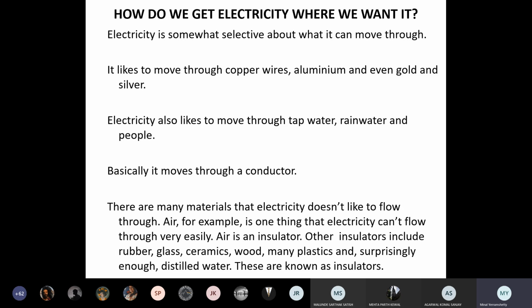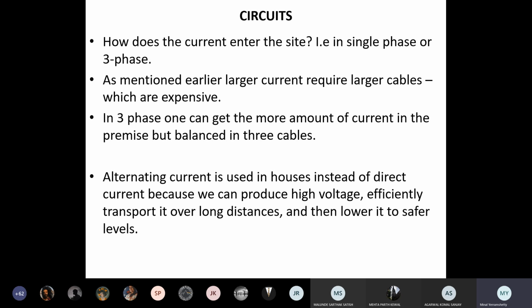And that's the reason why we have a plastic or rubber insulation around the live wire. Then you will see something in our college, this black colour thing. That is actually a thickened PVC covering, which works like a conduit, and it's very difficult to bend. It is bendable, I'm not saying you can bend it easily, but compared to a wire, you can fold a wire and keep it in your purse or pocket. The conduits cannot be folded like that because they are stiffer, and so they protect the wire within. So you have that conduit, and then you have the wires running in it. Not the live wires, the insulated wires.